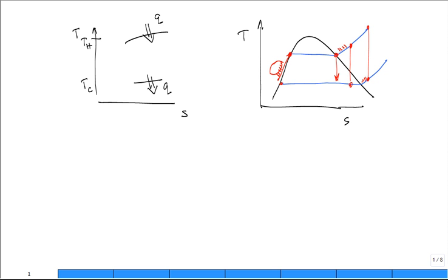So the two strategies we'll talk about today are superheat, where you superheat the steam, not just have saturated vapor going into the turbine, and then what they call regeneration. That is using some lower value steam to mix with the feed water before it goes into the steam generator, to bring up the temperature of the feed water from here up to there without using the heat source from maybe your coal or natural gas or nuclear power plant.